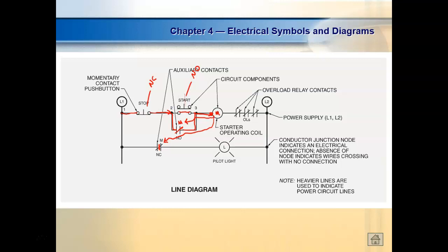It's also called a sealed-in circuit because it does what? It seals itself in, and some people call it a memory circuit. But this is a standard, what we call a start-stop circuit. How do I stop this thing? What's this running? Stop button. Now this is the control circuit.